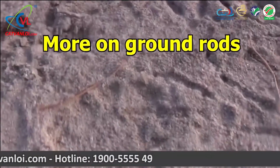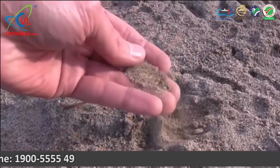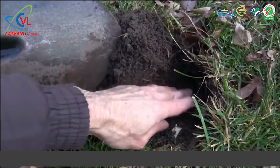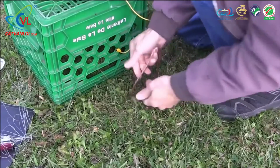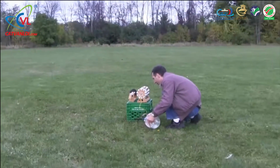For a ground rod to work well, the ground does have to be electrically conductive though, meaning it has a low resistance. Dry sand like this is not very conductive, and is a bad ground. But moist soil is fairly conductive, and is a better ground. Also, the more ground you connect to, the better. Here I just pushed some wires into the ground, and it wasn't very good. I even poured water in to help, but it still wasn't good.